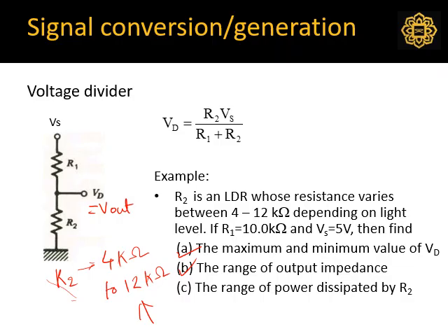So the thing that I was discussing is that you have to convert the signal into a reasonable electrical equivalent, like either voltage or current, so that we can measure it using electronic circuits. So a thermistor changes resistance with temperature, so you have to attach it to a voltage divider circuit or a Wheatstone bridge circuit to measure the change in the resistance as a proper voltage output.